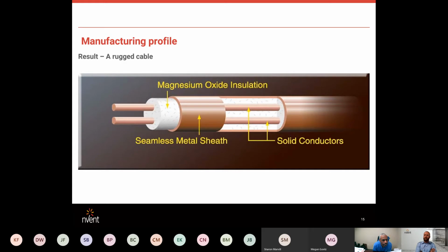You would get this tubing sent out to you, and it's pre-terminated. The power connection end and the end cap where it is terminated is already pre-terminated and done for you. There is no termination of those actual solid conductors done in the field. For example, when this starts out, like I mentioned, let's say the OD of that seamless metal sheath is 3/8 or 1/4 inch.